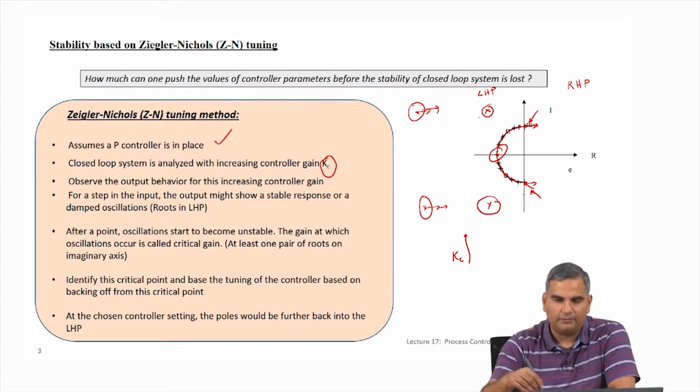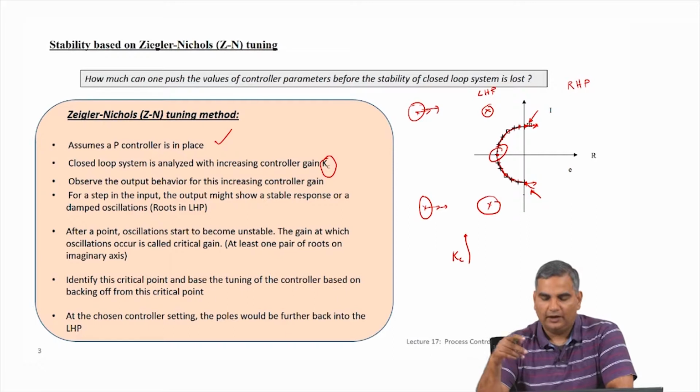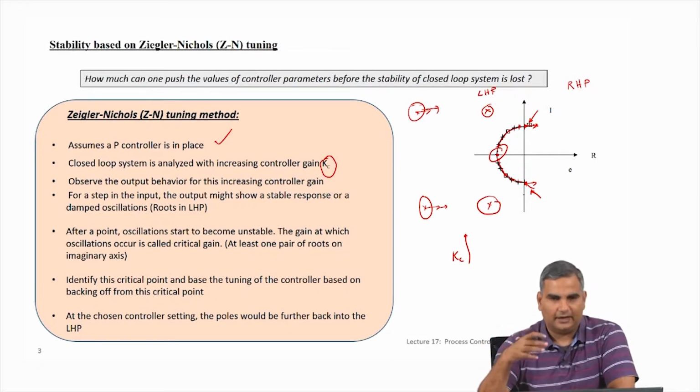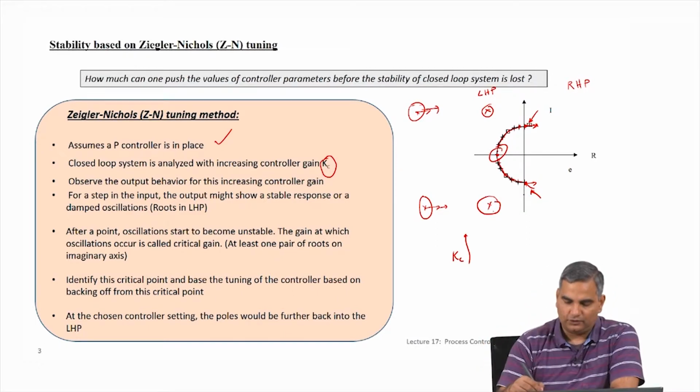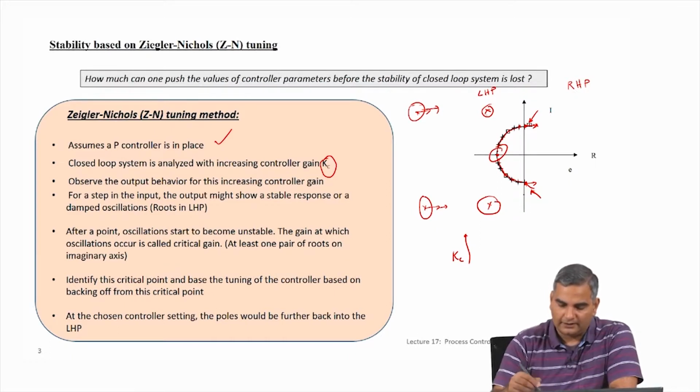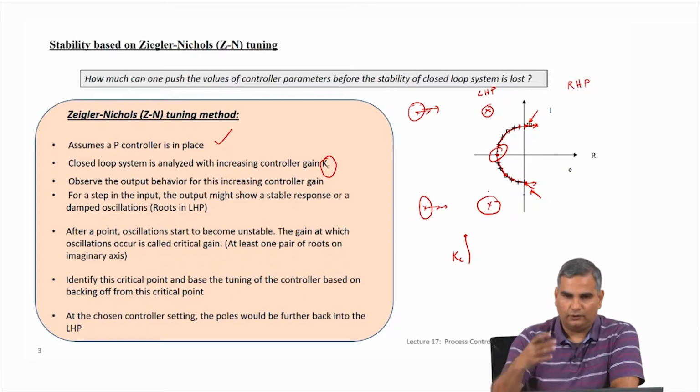So, the oscillations will be damped out after a while. After a little bit of transients dying out, the effect of these poles in terms of oscillations will die down, because while I will have a cos and sine term because of the imaginary part of these roots, the real part is less than 0. So, we know that it will basically make the amplitude 0.